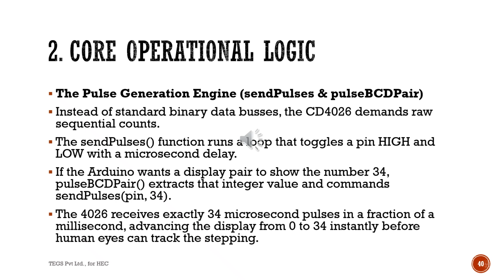2. Core operational logic. The pulse generation engine. The sync pulse and pulse BCD pair functions are the key component of this code. Instead of standard library data buses, the CD4026 demands a raw sequential count. The sync pulse function runs a loop that toggles the pin high and low with a microsecond delay.